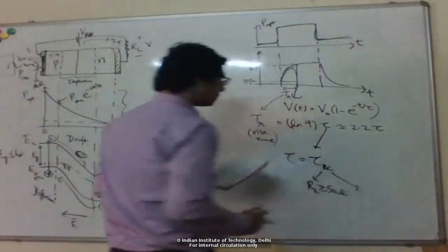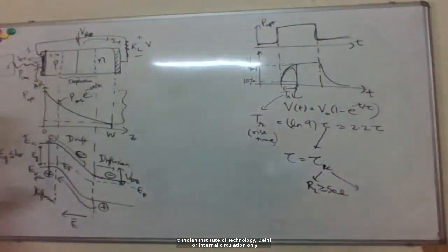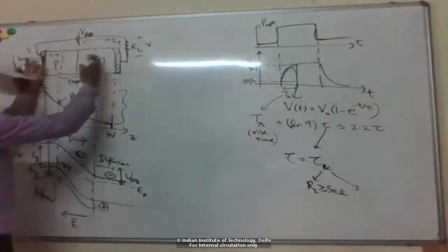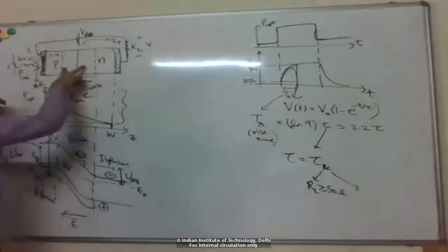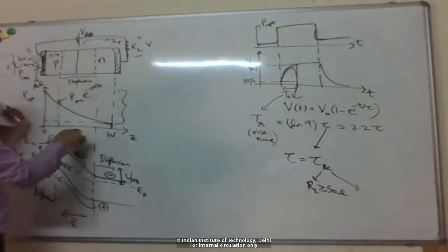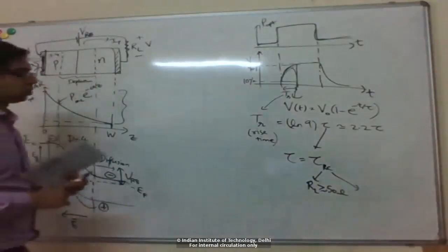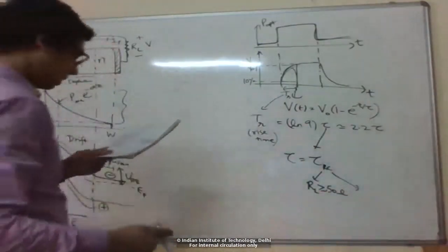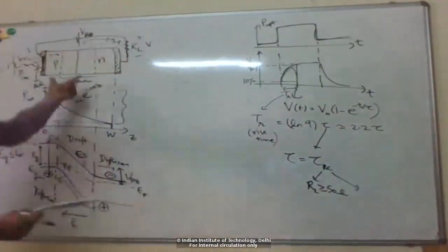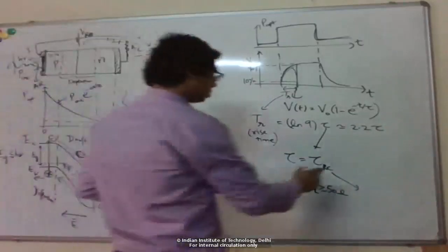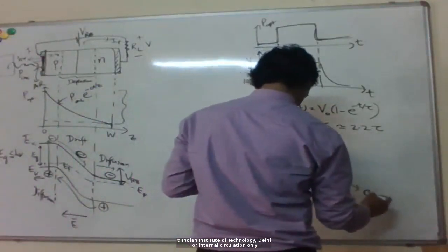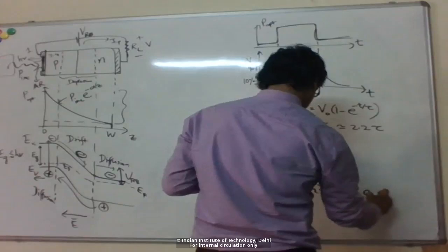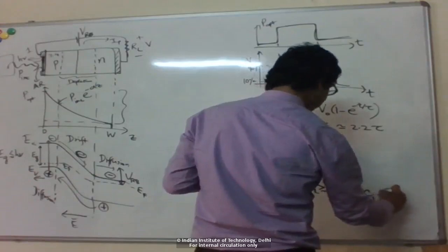Okay, and then the capacitance, as I said, is basically the capacitance of the device. If you think of this as some parallel plate capacitor here, right? It's like a dielectric of width something proportional to W. And you know, the capacitance for a parallel plate capacitor goes inversely with the distance between the plates. So this capacitance here is basically the device capacitance from the PN junction, also known as junction capacitance.